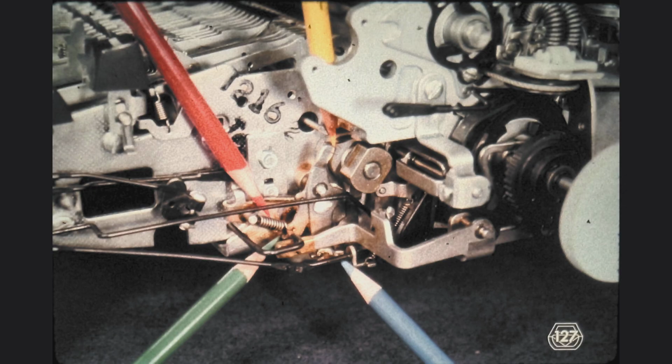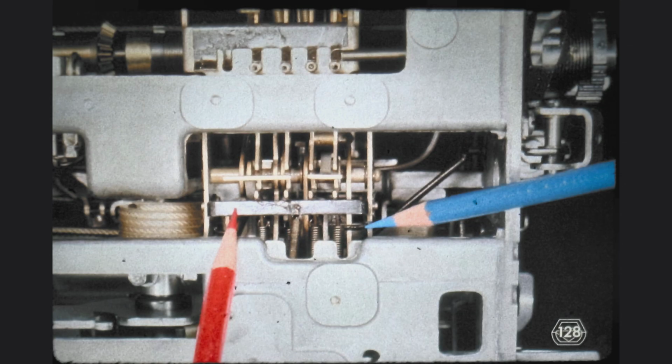On the other hand, if we do not allow for this clearance, we may print some or all of the characters at low printing velocity. The operational interposers are restored by the bail indicated by the red pencil. The bail is rotated directly by the operational cam followers when they act on either one of the 2 lugs on the sides of the bail, at the blue pencil.